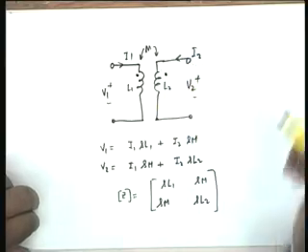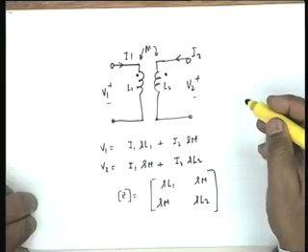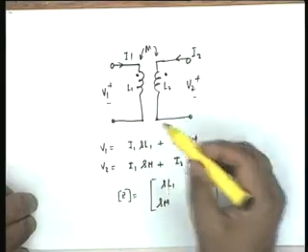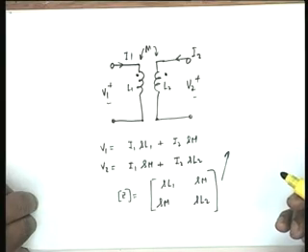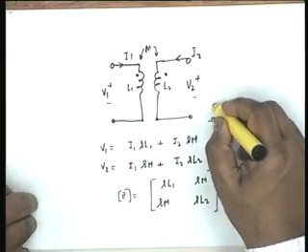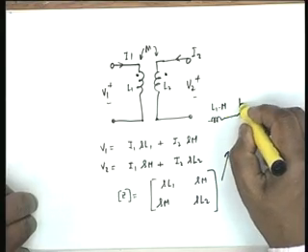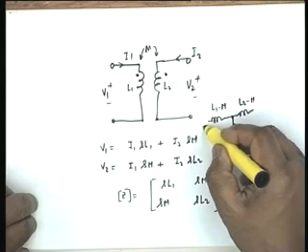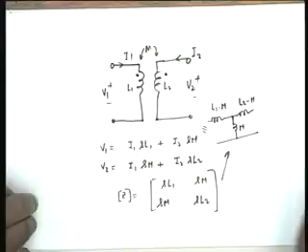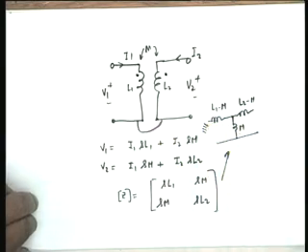So, this is non-ideal, and you see the Z parameters are obtained by inspection, and you also know that if these two terminals are connected, so it is a 3-terminal network, then these Z parameters can be represented by the T equivalent circuit, and the equivalent circuit would be L1 minus M, that is Z11 minus Z12, L2 minus M, and Z12 shall be equal to M. This would be equivalent to this provided this red colored connection is there, pink colored connection.